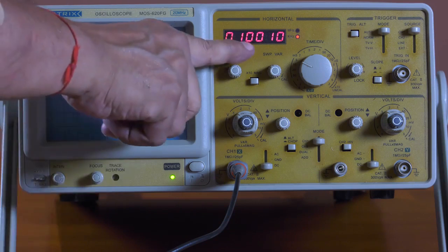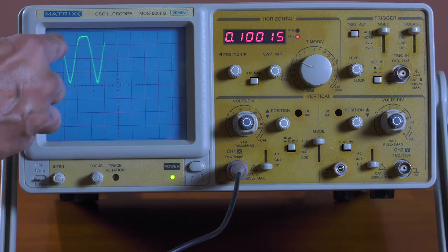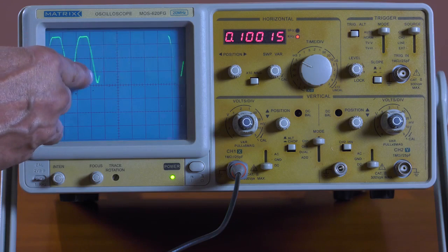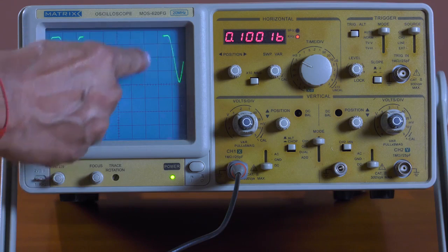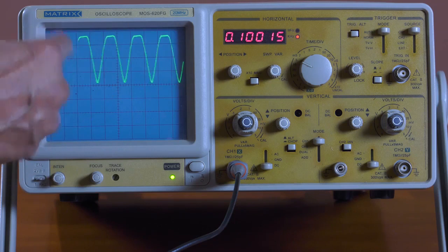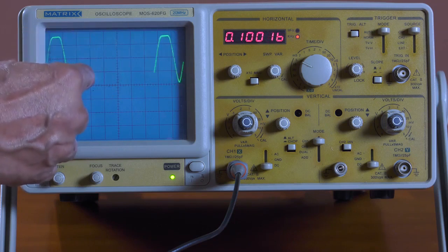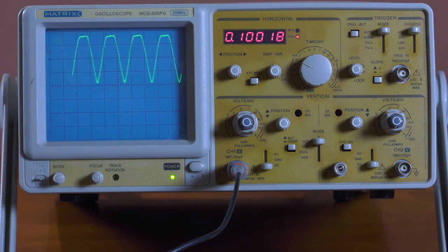Look what's happened to the frequency. The frequency has now doubled from 50 to 100 hertz. So already we are getting a slightly higher frequency power supply, which makes it efficient, number one. Number two, the positive half cycle for each part of the sine wave is now used. If you look at my fingers, you will see that. There's no more gap here like you saw with the half wave rectifier. Each part of the sine wave, the positive half cycle and the negative half cycle, is being utilized, which makes it a very efficient power supply.